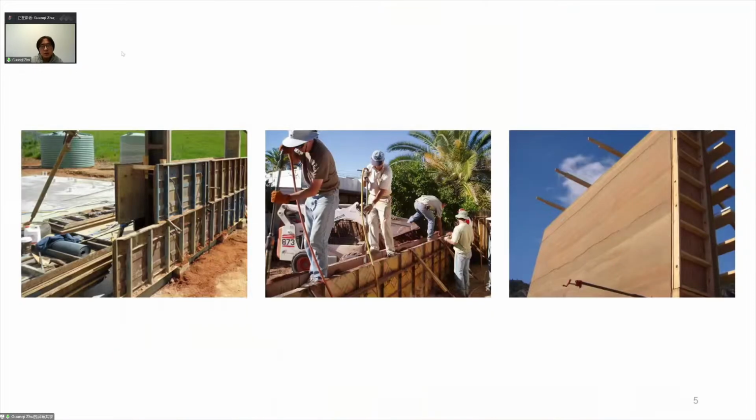This group of pictures illustrates how a traditional rammed earth wall can be fabricated. For the first image, we can see the workers need to build a large metal formwork, totally the same as in concrete construction. In the second, the workers pour the earth material into this mold, standing on the mold and using pneumatic hammers to compress the earth together. It only takes around 7 days, rather than 3 or 4 weeks as in concrete construction. You can then just remove the molds, and this is the final outcome.